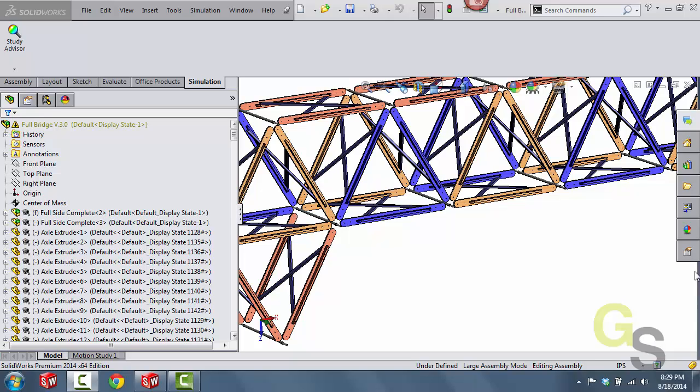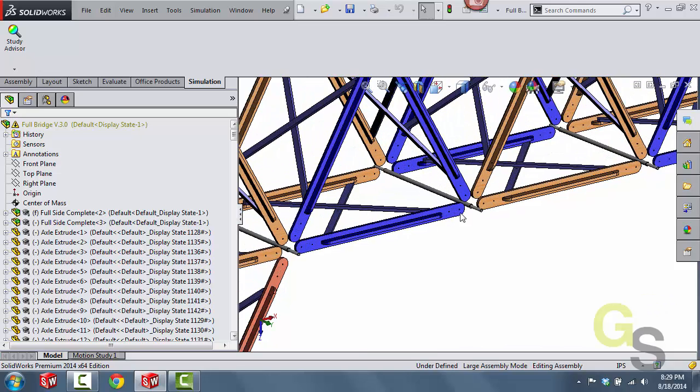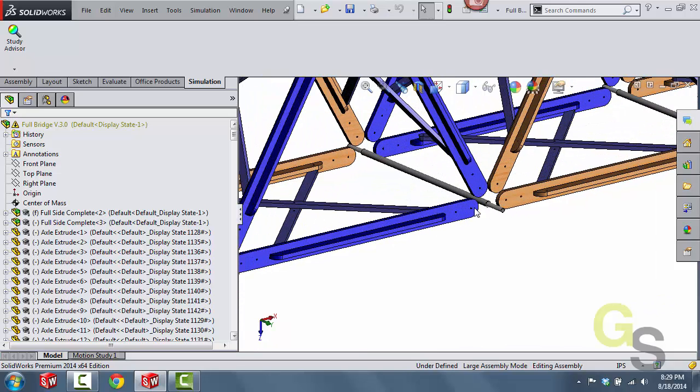And that's because what you can do with beams is you can edit the joint groups. Now remember, a joint occurs at the end of a beam, and once two beams meet up and their joints seem like they're going to intersect, those joints will merge as one and create one joint. And when working with beams, you can edit or manipulate the joint groups to make your model a little bit more stable. And that's what we're going to do.